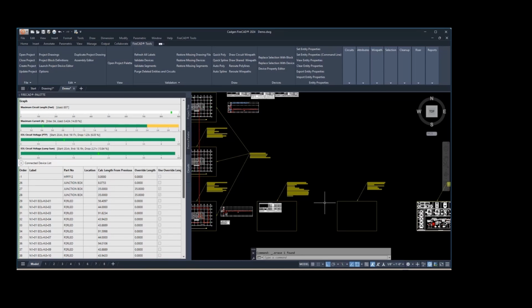So, modifications from the riser. All the modifications you have to perform are floor plan based, and then you check the riser as a check, or can you vice versa work backwards? Meaning, if there was something like you noticed earlier, like a control module connected, and you saw it wasn't shown in a riser, can you modify from the riser and update vice versa to the plan? No, it only goes one direction from the floor plan to the riser.